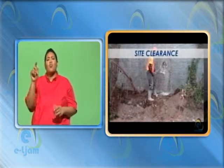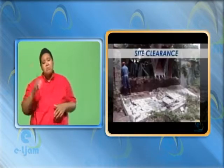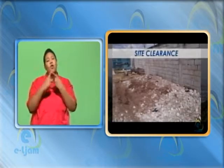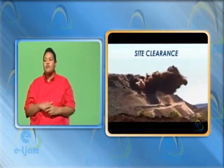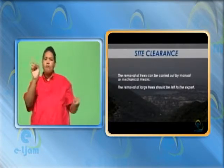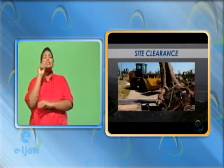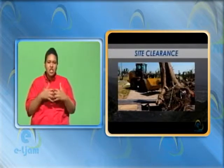This may involve the demolition of existing buildings, the grubbing out of bushes and trees, and the removal of soil to reduce levels. Demolition is a skilled occupation and should only be tackled by a skilled demolition contractor. The removal of trees can be carried out by manual or mechanical means. The removal of large trees should be left to the expert.